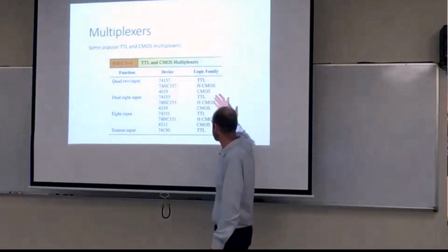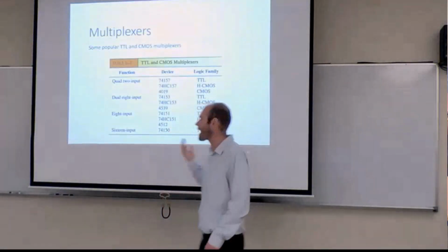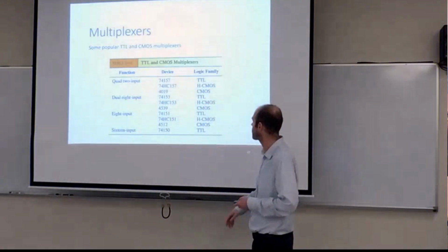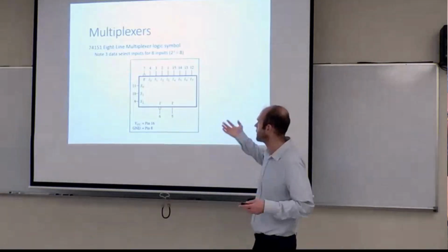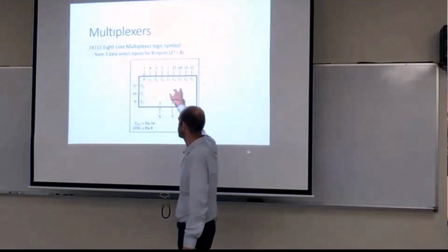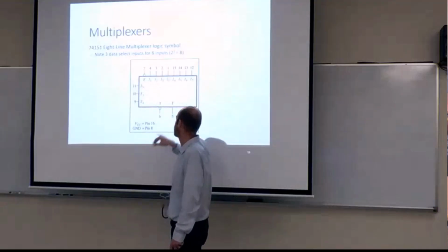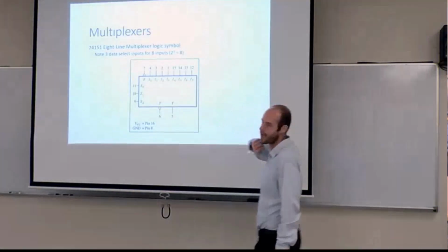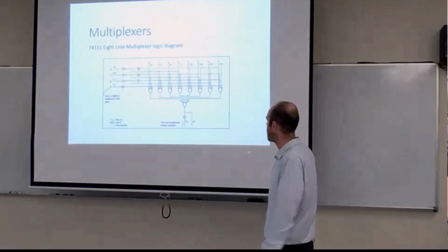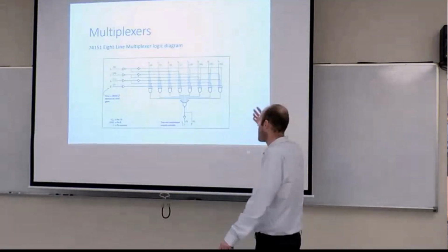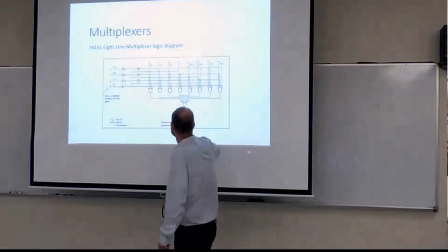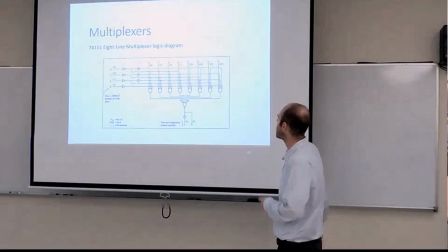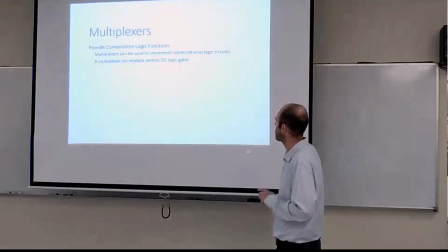There are a lot of industry standardized packages. You can just buy a multiplexer with so many input pins and output pins. And you would see a data sheet that looks something like this, where you have a bunch of different inputs. You have your selection bits, then you have a couple outputs, with Y and Y not, so active high, active low outputs. Data sheets would include your internal logic, but it's essentially using AND enabling to make that multiplexing work.